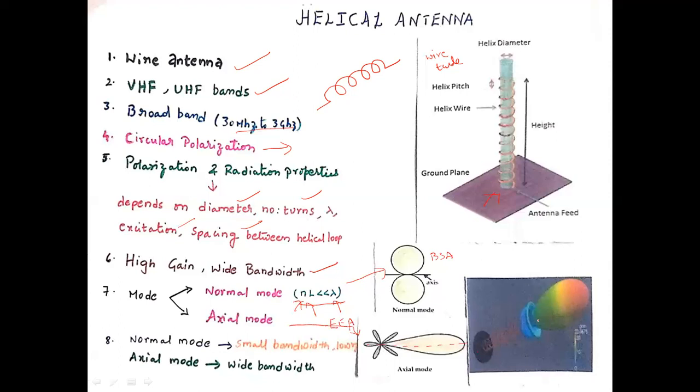Here in this you can watch. This is the helix and this is our ground plane. The helix operated in this direction produces the output in this particular direction. From this we can observe that the way we orient our helical antenna, based on the orientation, determines the output radiation pattern. All the combined radiation pattern will be available in this direction, from all these three helix outputs.